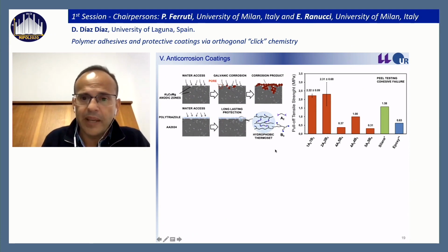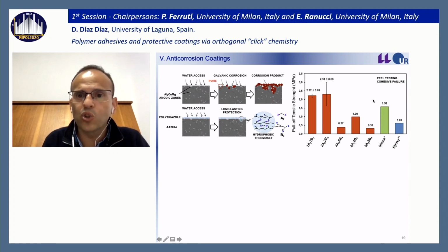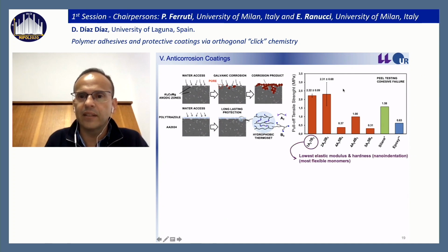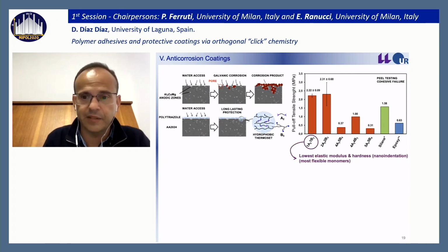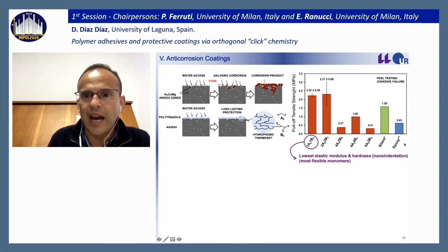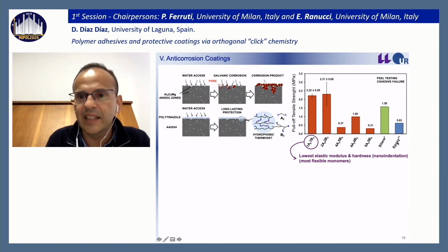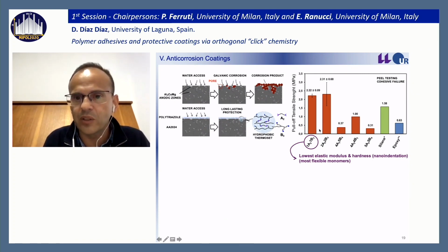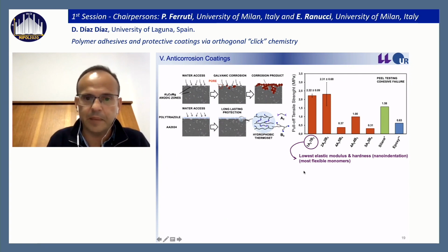And also the best monomers that we use for anti-corrosion also provide, as you can see in this plot, the highest strength of the adhesive, right? So we have some monomers or some combinations that provide a very nice adhesive through a cohesive failure of the adhesive. And if you compare that with the silane and the epoxy layer, they stick even stronger to the surface.